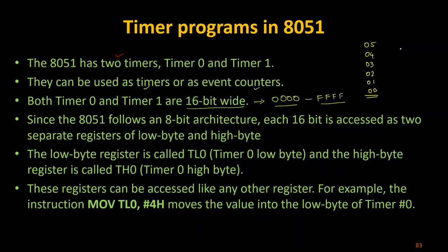Here it is going to be a little different. Assume the value we give is FFF0. Your count values will start counting with FFF1, FFF2, and so on, all of them FF.., until it counts up to FFFF. So the total here is 16 counts. In 8086, we can directly give the count as 05, and it starts its count from 05 and reaches 0.